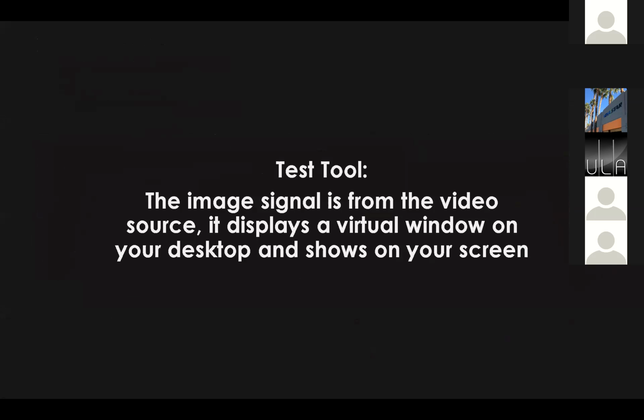Another useful function is test2, which displays some color patterns on the computer, and so on the LED screen too. The test2 function is quite helpful when we need to check if the LED is displaying pixel to pixel, and also to locate abnormal components or modules in the center of the LED screen.